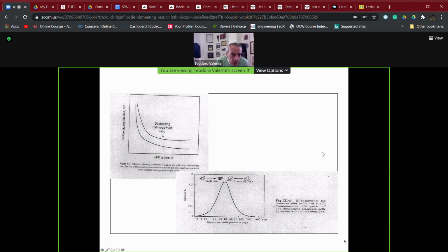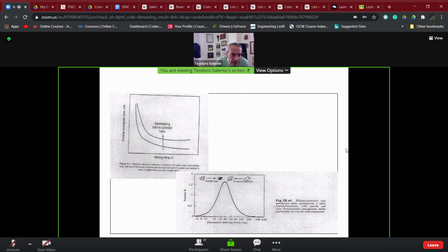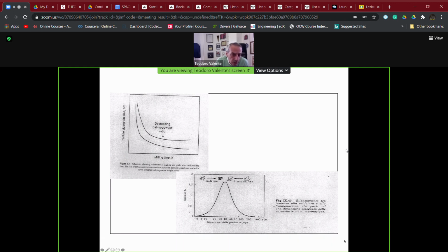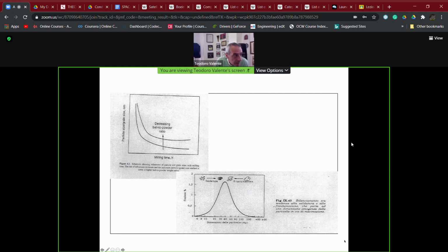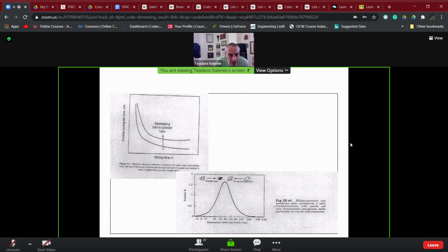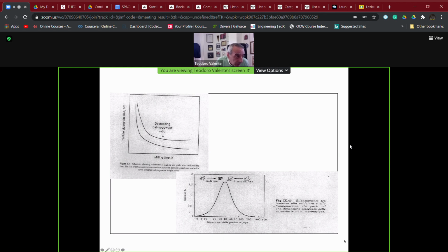Why is this going to happen? Because we do have, at the same time, looking at the mechanical interaction between the balls, which are inside the vials, and the powders, which are put inside the vial, two phenomena. The first phenomenon is related to the impact of balls with the fed powders inside the mills. Impact, that is an impulsive load.